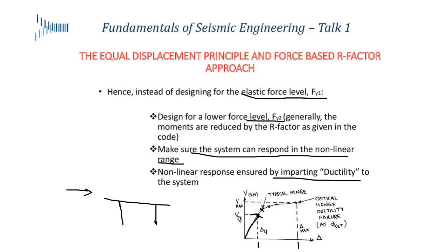So as soon as my first hinge forms, I'm not basically just destroying my structure. If I can keep forming those hinges at different points, and the hinges can keep operating properly, i.e. they don't just disintegrate, and we'll talk about how to design those hinges to keep them functional, then I've done a good design.